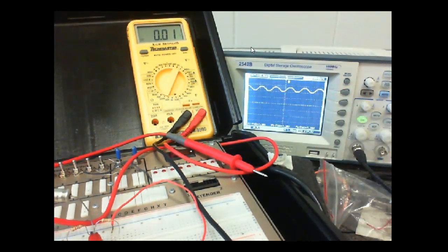So that means we can measure the bias when there's AC on the circuit. On your amplifiers, you're checking the bias on the transistor, and you've got it turned up wide open, and you're not saturating the transistors, the bias will still be right, because your meter's going to go right down the center of that AC signal. But you have to put your meter on DC. Then it ignores the what? It ignores the AC. So what's the DC average of an AC sine wave?